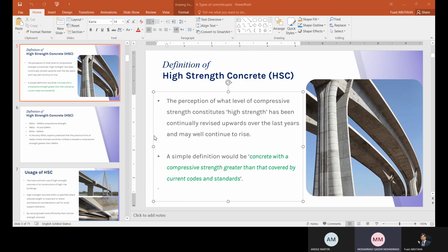Yeah, mix one has the lower maximum size, or let's say, just focus on the aggregate. I have two aggregates, the same contents in both mixes. The first one, the aggregate size is ranging between 4.75 up to 14. The second one, 4.75 ranging up to 20. So this is mix 2 that has the higher maximum size. So mix 1, mix 2, which one gives higher strength?